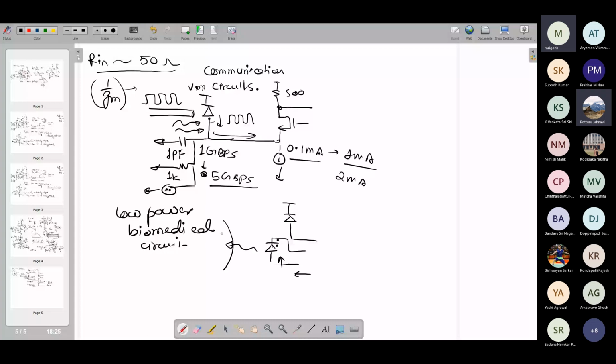and depending upon the blood velocity that you have under your skin, the reflected light may have some shift in the amplitude and phase. So basically there is a Doppler kind of effect, because of which the light undergoes some shift. The light phase and amplitude may have some shift because of the blood flow just below the skin. And that change in amplitude has to be detected. That change in phase has to be detected. So for that, once again, the change becomes important. Here it is not the absolute signal level, but we are trying to detect that small change.